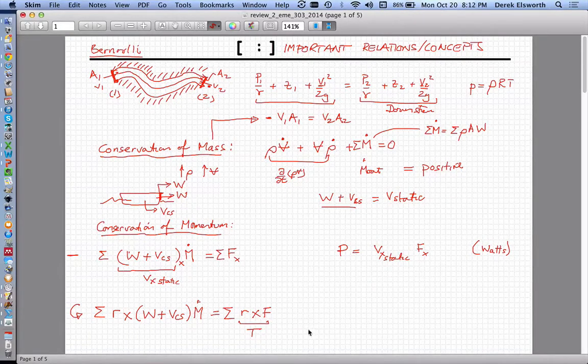In terms of a diagram, if you see fluid popping out of here relative to this arc, then this is the radius. This is V theta, which is what we want. So this is V theta static, if you like. So it has to be resolved in that way. What else? I suppose this would be the force that we'd have to apply. Let's at least be true to the sign convention. This is the force, and of course the torque would just be the force times the radius.